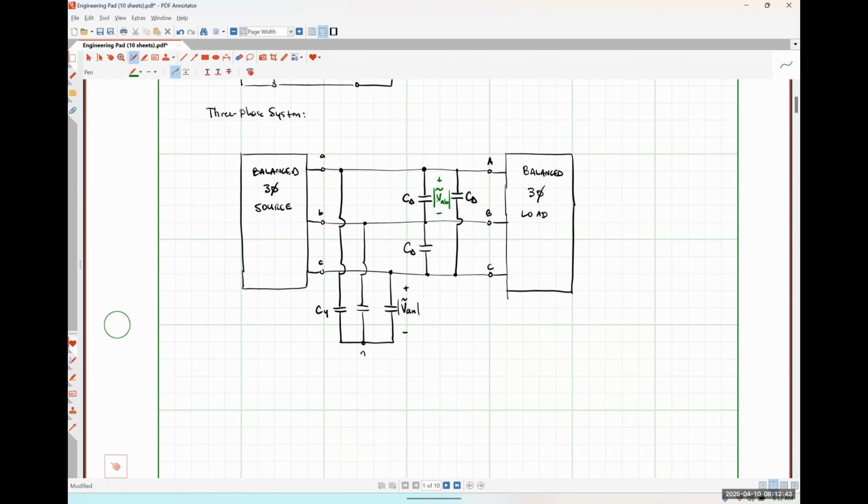I don't know how many of you have ever had to go out and buy a capacitor for anything at this point in your careers. Might not be many of you, but capacitors are rated based on the amount of voltage drop that they can see, right? Because the delta connected capacitors have to see a higher voltage, they might be slightly more expensive. So it's really just going to be a cost analysis that tells you which type of capacitor bank you should connect. Can you get larger, cheaper capacitors that see a smaller voltage, or can you get less expensive, smaller capacitors that see a larger voltage? Whichever one comes out to be the most cost savings is the one that you will go with. Okay.